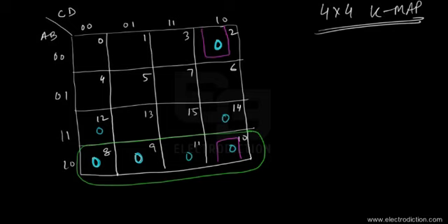And then we can use some other color. Let's see. Okay, let's just use this color over here. Then we can get another group. If we fold the Karnaugh map sideways once again, then we can see that the cells 12 and 8 come adjacent to the cells 10 and 14. So once again we have another group over here consisting of another quad. So we have 2 quads and a single duplet. Okay, so let's just write the expressions for each of the groups.